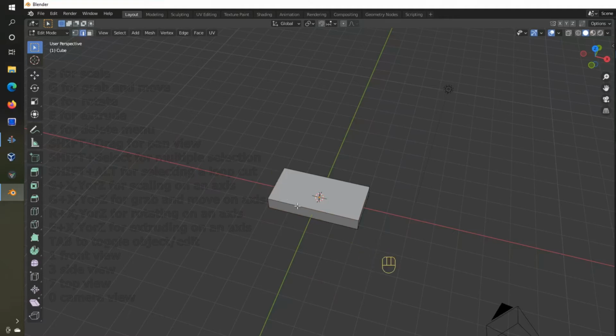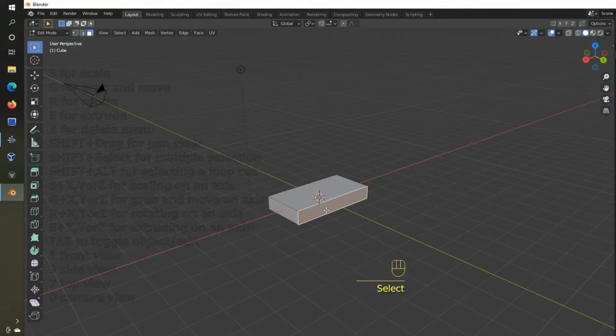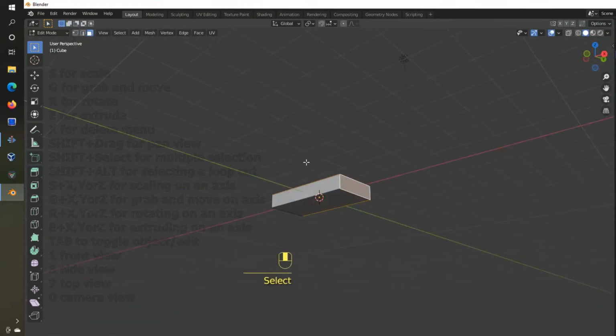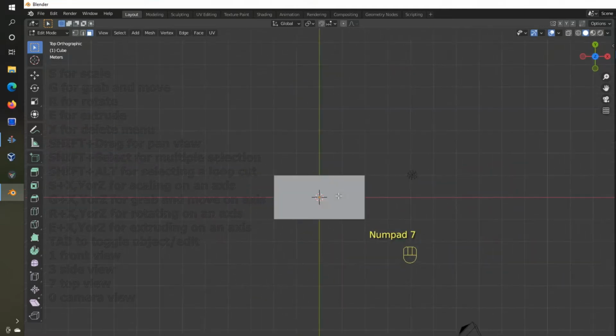So you can see them there. Then you can select the edge select and shift select if you want to select multiple edges or faces. The face tool, same sort of thing. If you shift select, you can select multiple faces. And that's how you make sure that you'll select everything. And A is select all.